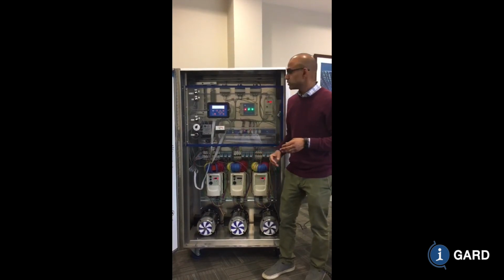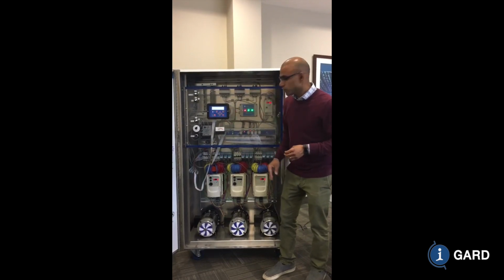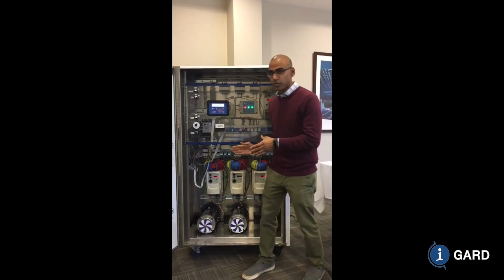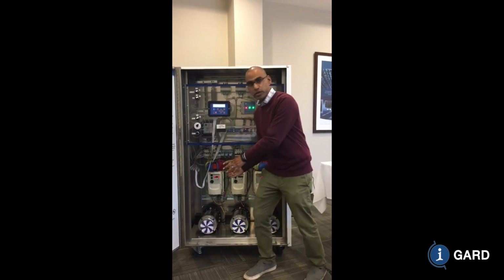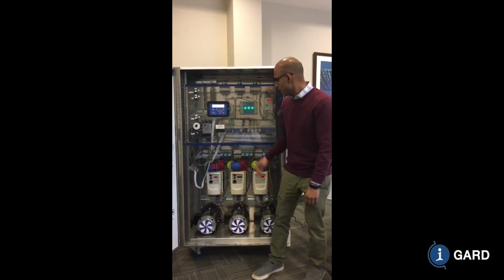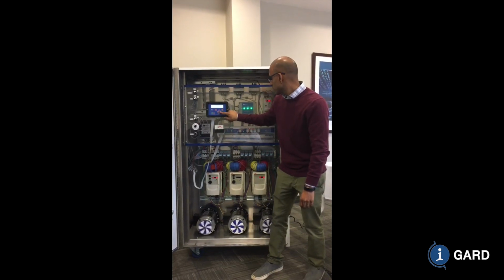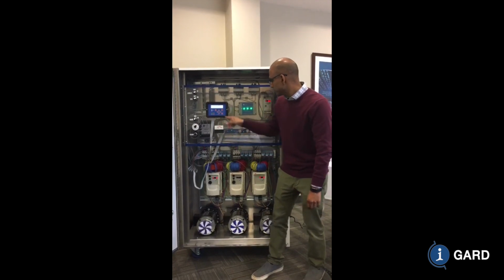In this sort of situation, what you do is turn pulsing on. From this point, you would find where your fault is. Oh, it's feeder 1, and I use pulsing to further locate it and clear that fault, and then locate the fault on feeder 2.